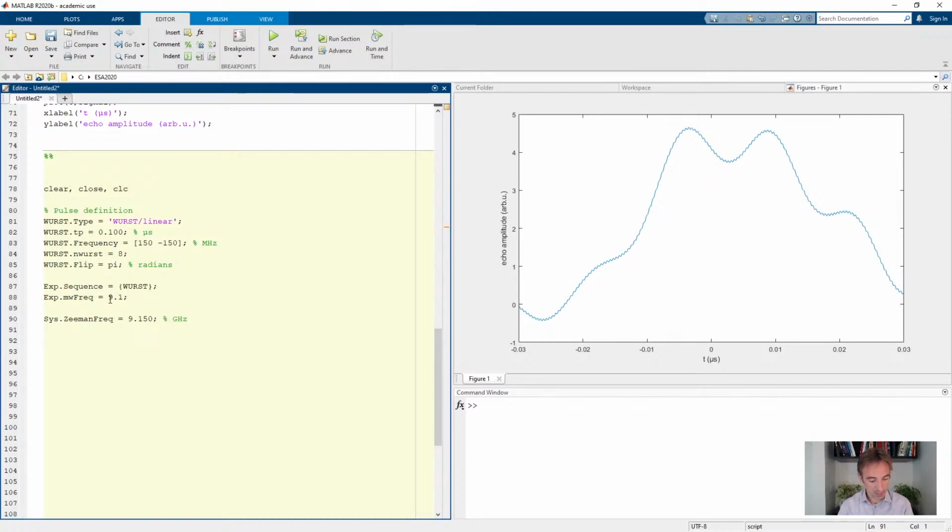the spin physics. Finally, let's specify some detection operators which you can choose freely, Z1 and plus1. So this would basically mean the Z component for the first spin and the plus component for the first spin. And also the detection frequency. We can change the detection frequency. Let's do 0 for the Z component and 9.1 to down convert the rotating plus 1 coherence from 9.1 gigahertz down to 0. All right, now we can run the simulation.